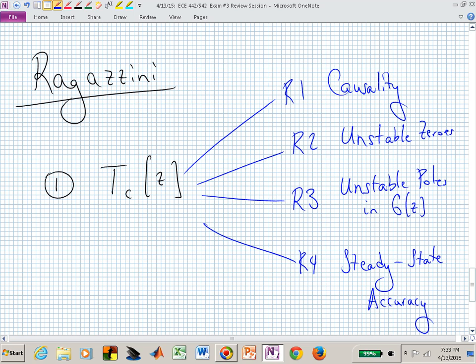You need to add some z's into the denominator. Z's not to fall asleep, but z's to make your pole zero excess better. And the best place to put those might be right at the origin. Just add one right at the origin. Now your denominator is third order. You have the correct pole zero excess.